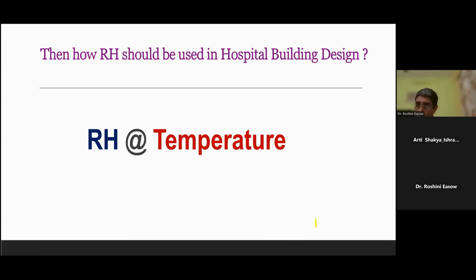So in these types of critical room designs, say surgical rooms and bone marrow transplantation rooms, this type of calculation with RH is not very effective for the design or for the patients, because we have to understand that we have to reduce the moisture even if it does not come down to the condensing level. So this is a very important thing.